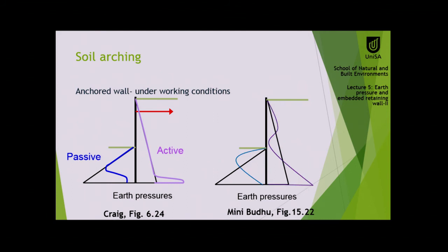The pressure diagram was this. It flexed over there. So the pressure increased beyond the Rankine theory, then decreased, then went beyond the Rankine theory again. It's a kind of arching over here. On two sides of the arch, you get higher pressure. Again, on the passive side, this goes up. It's always the same case.